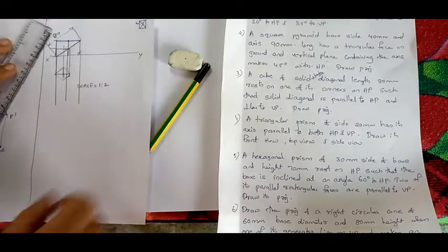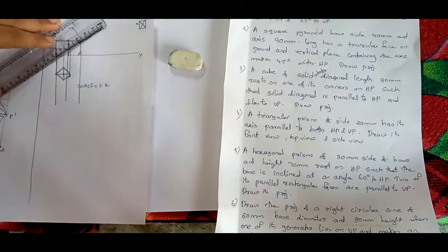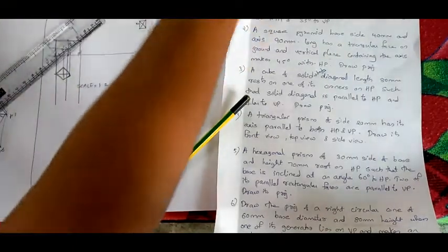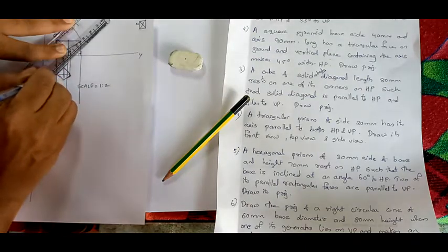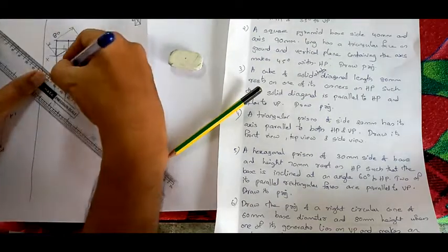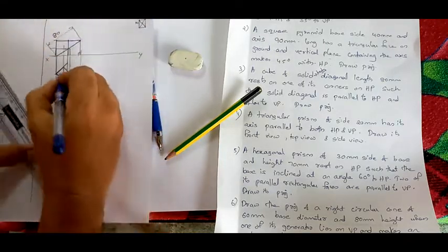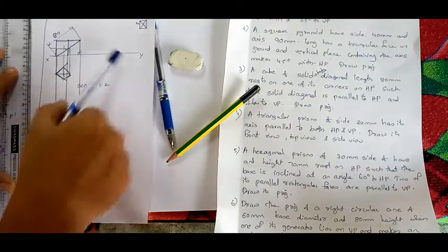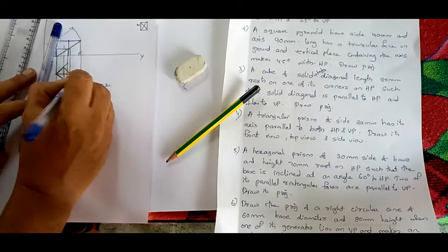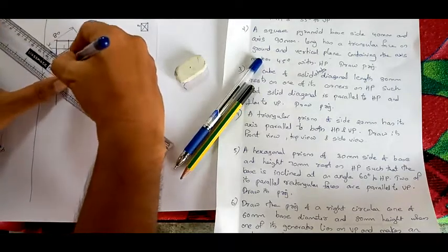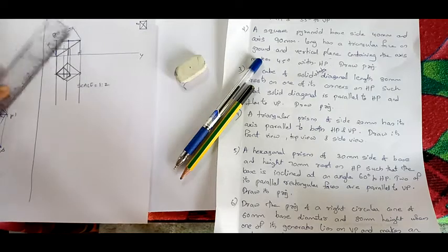Now you have already constructed a square here, right? Now what I am going to do is extend this to the center line. Similarly, extend this line to the center line. Now with this horizontal line I will extend to this, find this point, and construct a square like this. So you will get a square.